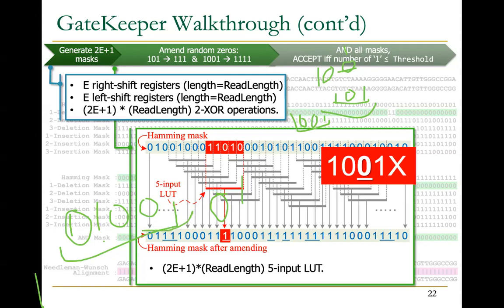That's why we consider 1, 0, 0, 1, and then something else, or a don't care next to it. If it is 1, still correct. If it is 0, still correct. But at least these ones, the one here and the one there, should be inside the pattern that we are checking so that we can say this is 1001. I hope this is clear. If it's not, I can explain it again. Just let me know in the chat box.